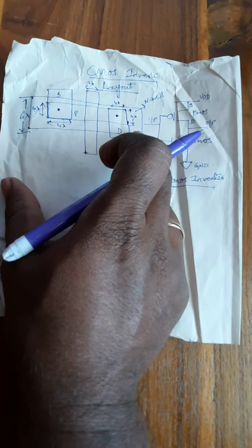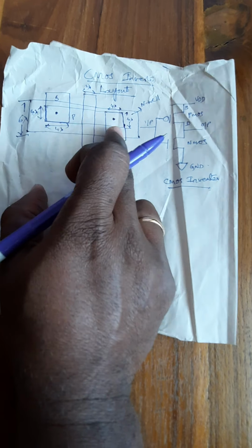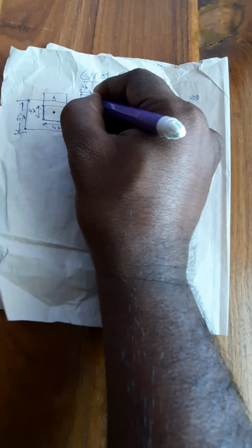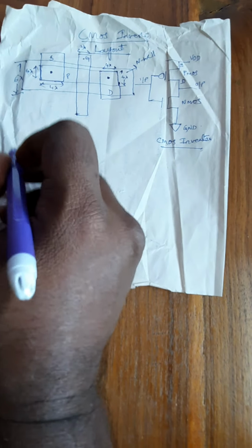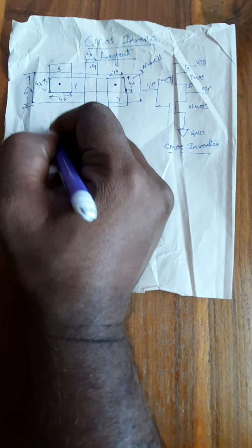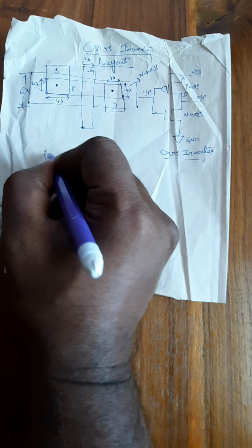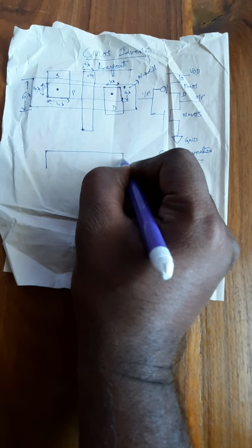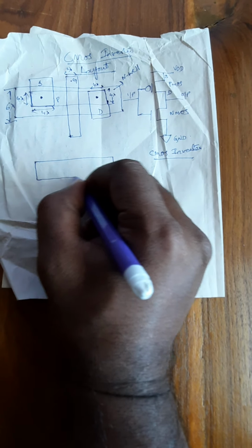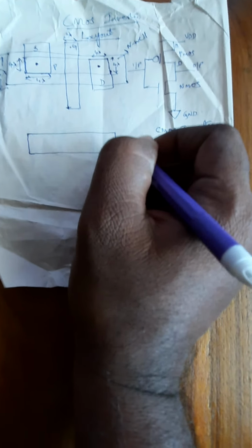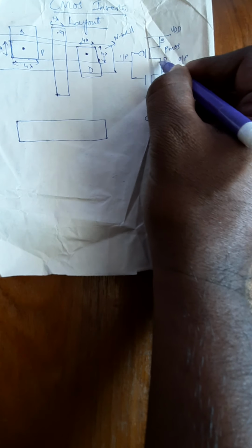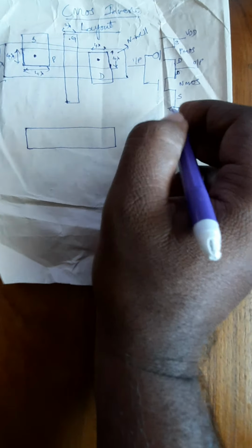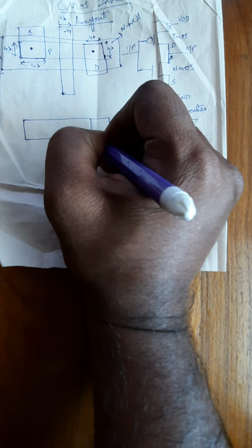Now once you have completed the source, drain and gate terminals of the PMOS, we'll go for the drawing of the NMOS. In a similar fashion, just below this one, exactly below the P diffusion, draw the N diffusion as a rectangular box. After that, you can see that the drain is in the upward direction and the source is in the downward direction. Since I need to connect both the drains over here, I'm taking this part as the drain.